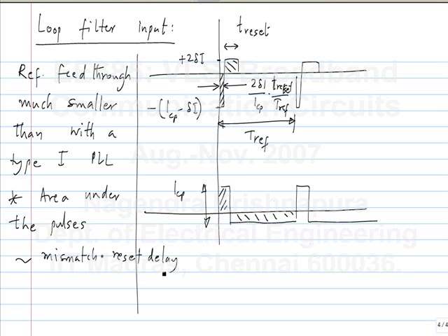Typical value of delta I. So, delta I by ICP can certainly make this better than 10%. So, this is the relative mismatch on the current sources, right, rather 2 delta I by ICP. You can match 2 current sources to better than that. I mean, at low frequencies, this matching can be 1% or something of that sort, right. It's not very difficult to do that.